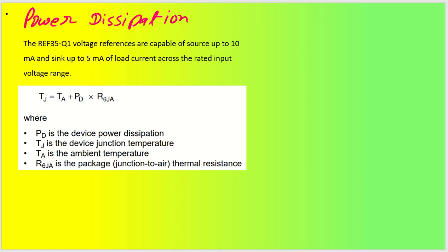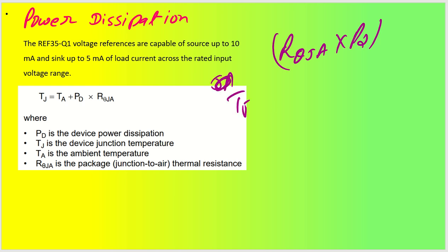Good. Now let us get into the design and power dissipation. As I told you, the theta RJA was there, multiplied by power dissipation, gives the delta T, and the temperature at the junction will be this plus the ambient temperature, which may be 25 degrees centigrade or maybe 30 degrees centigrade of your environment, that much you can add. So that will be the total temperature at the junction of the IC. This is very simple, as I have already given you the example.